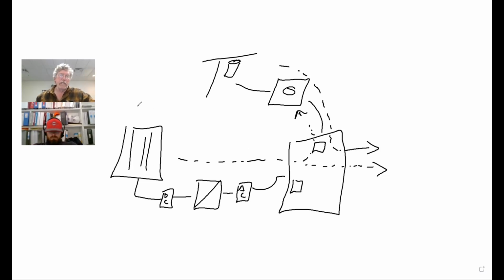But it's important not to think that if I've got a 5 kW array, I've got to have a 5 kW inverter, because while they are related, they do not have to be the same thing. And that's where we get into the whole concept of clipping. I don't want to confuse this question with that, but they are related, but they're not exactly the same thing. Hopefully I haven't confused you with that.